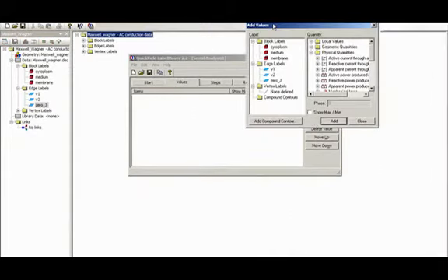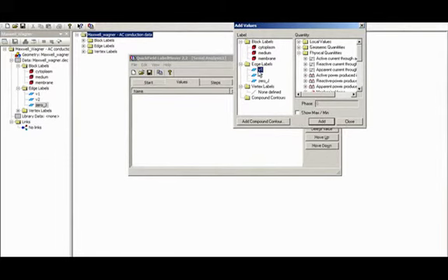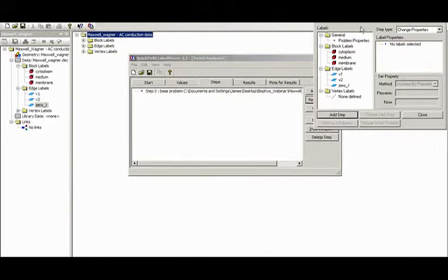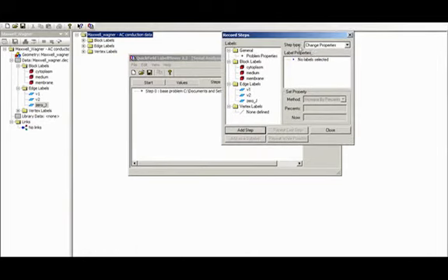This is the Add Values window. I'm going to choose the left boundary of the model and look at the active current. Let's add that. Also, I want to look at the reactive and the apparent current densities. Now we want to record steps. This is the Record Steps window, and I'm going to change the problem properties. The property that I'm going to change is the frequency.